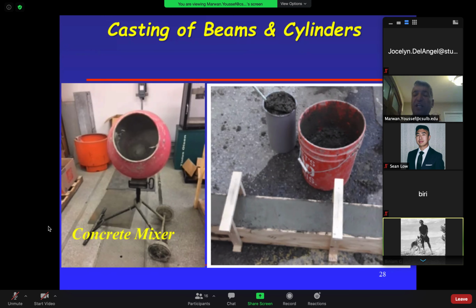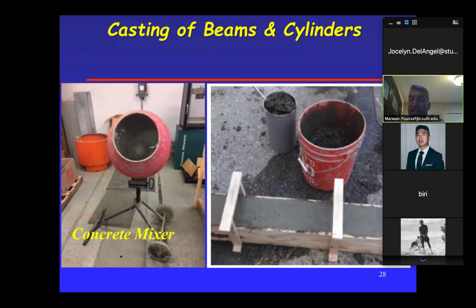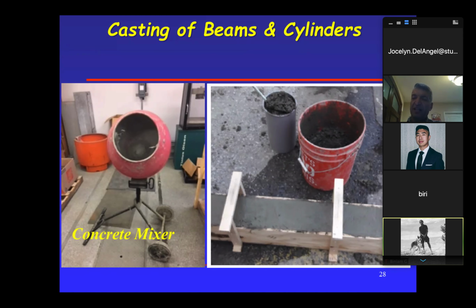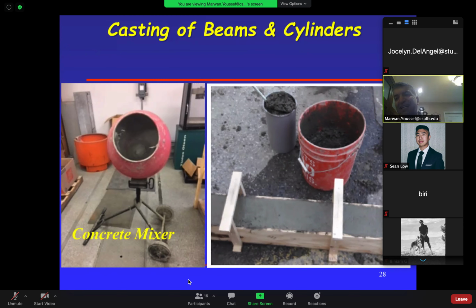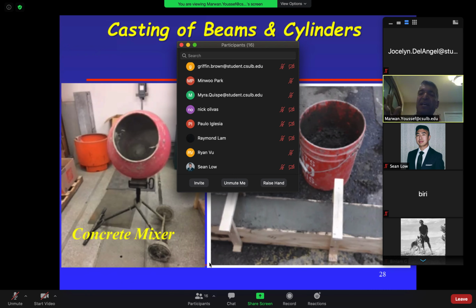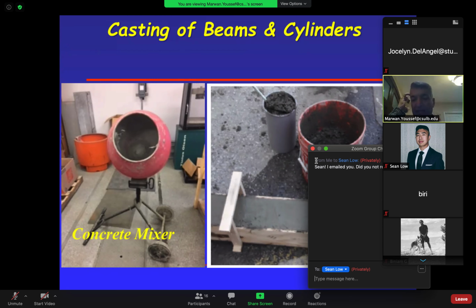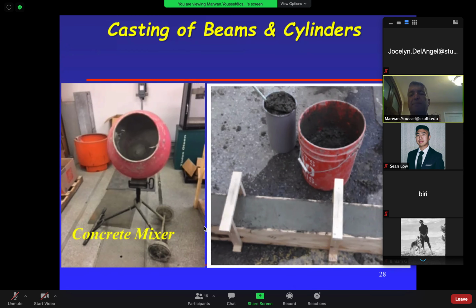All the concrete truck does is they attach a chute to the end, and they have two ways. If you're pouring a footing below ground, the chute is put on, and by gravity the concrete will flow down. But if you are pouring a slab, the ready mix truck dumps into a big pump, and then the pump pumps it up. So if gravity doesn't do it, then you have to pump it. Does that make sense?